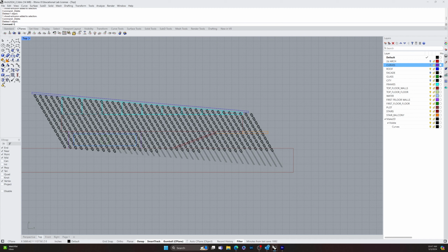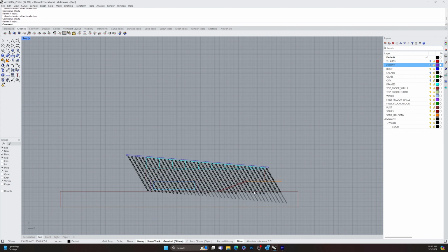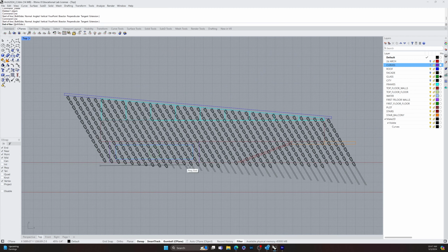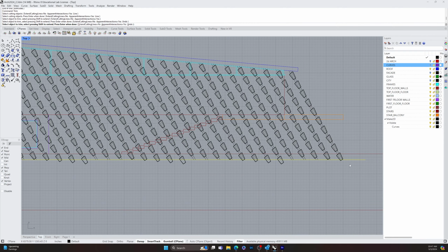It actually looks kind of cool. I think they're kind of dropping into the water. And then this, I think we'll get rid of too. That last hole. Okay. And then I'm going to draw a line, right around here, with ortho on, shift. And then I want to trim, cutting line here, enter, all of these off just to get rid of any unnecessary extra length.